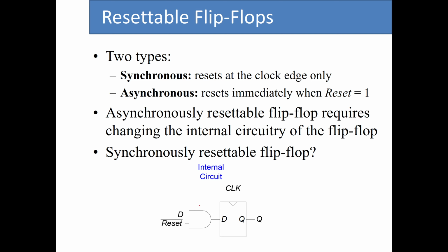This is the internal design of a synchronous resettable flip-flop. As you can see, when the reset signal is 1, that makes reset bar 0. That makes the output of this AND gate 0. So when you make reset 1, you make the data input of the flip-flop 0.